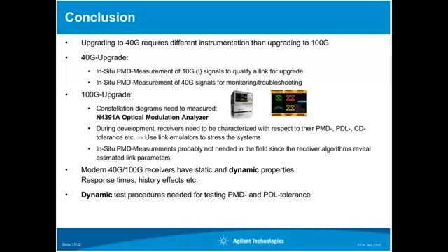And once you have the PMD coefficient, you have the full information about the first and second order statistics. So measuring the effective DGD is just a vehicle to get to the PMD coefficient. On the other hand, it's also a way to measure your momentary distortions. So in that area, it might be interesting to be able to measure second order. At the moment, this is not implemented yet. So the effective DGD more or less focuses on first order distortions to get to the PMD coefficient in the end.